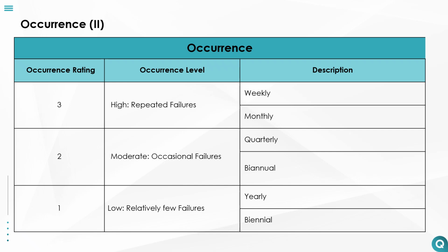An occurrence rating of 1 would include something such as an advanced filtration system used in the production of sterile injectable drugs, which has an extremely low probability of causing contamination due to its high quality design and rigorous maintenance schedule. Historical data and preventative measures show that batch-to-batch contamination has occurred less than once every 4 years. This very rare likelihood of occurrence would be assigned an occurrence rating of 1, indicating a remote chance of failure.